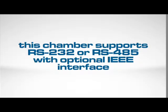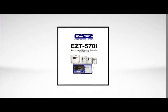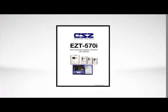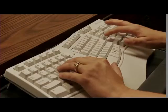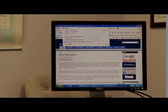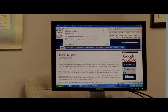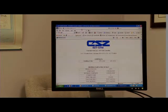This chamber supports both RS-232 or RS-485 as standard with optional IEEE Interface. The EZT570i uses Modbus RTU protocol. For information on setting up communications, please refer to the EZT570i controller manual. With the new EZT570i, users may activate Ethernet to monitor the chamber using a web browser or monitor and control the chamber from a PC using a VNC server viewer, which displays the EZT570i graphic interface directly on the PC screen, as if controlling directly from the chamber.